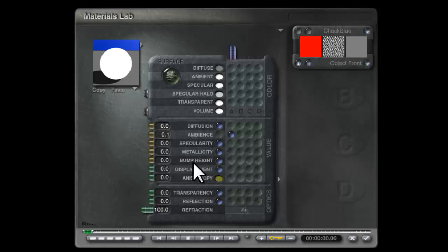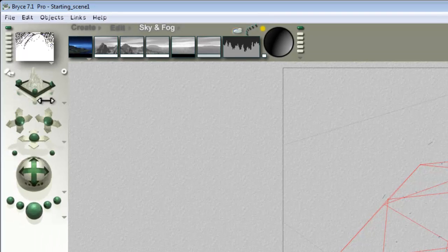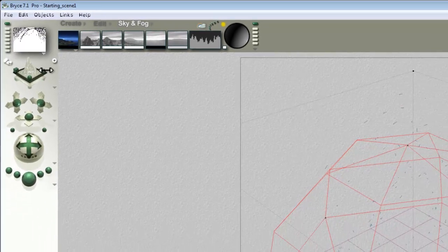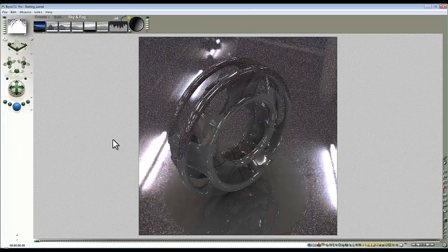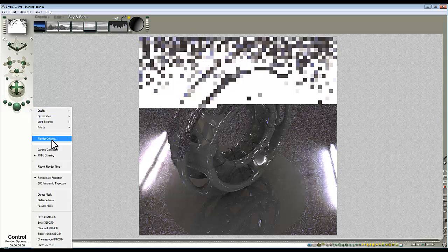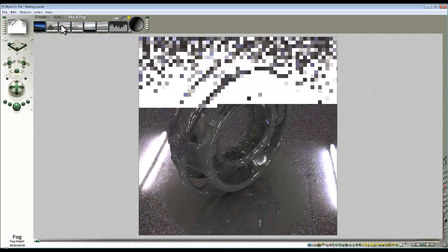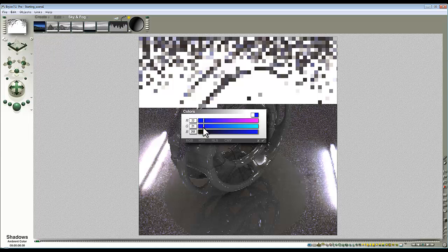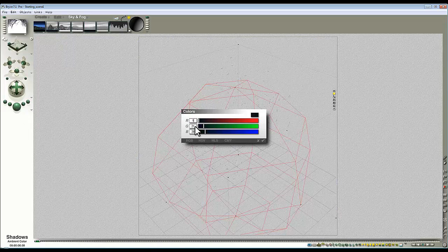Still looks extraordinarily bright. I mean, it wouldn't do if it was under normal circumstances, but this output's really boosting it from the hypertexture. So that's very high output now, and probably you can see in the preview there, because I've got this set to accurate rendering, which shows the transient rendering effect, that it's all gone a bit too bright. So in render options I'll just set this back down to 4 so we can preview this, and then I'll modify the global ambient colour now down to see if we can just get it into a level where we can see what's going off.